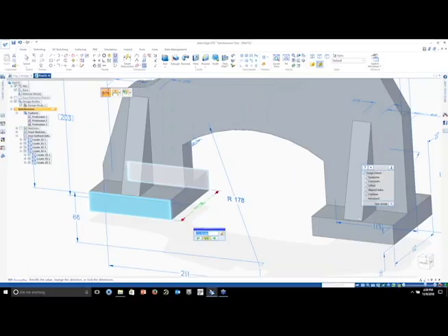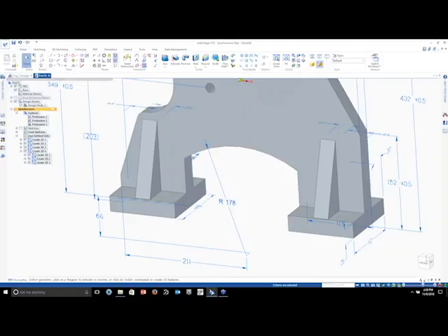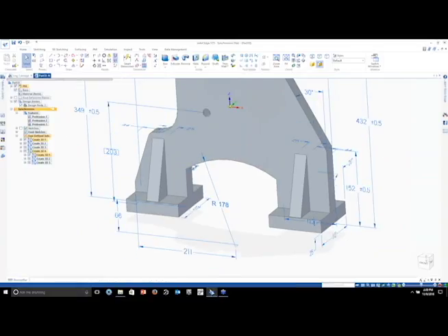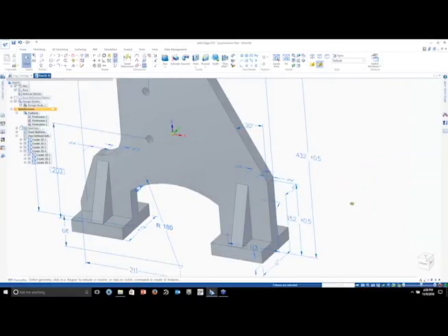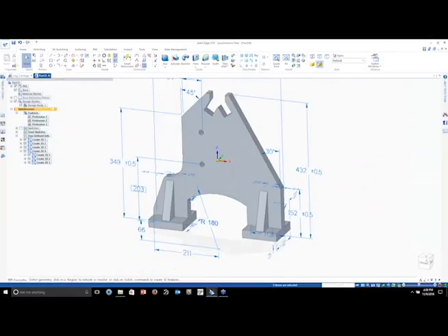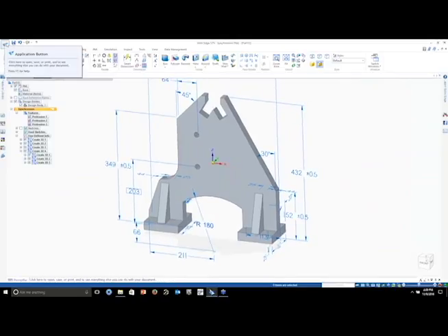So, that's a real huge time saver. So if you wanted to, we'll just save this and show you. Wanted to bring it right back into Draft. So I create a drawing of the active model. So again, I'll be creating sketches from my 3D. So let's scale that, bring that view, an ISO view, in.